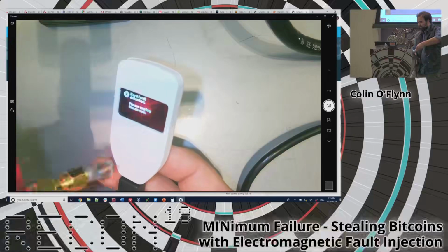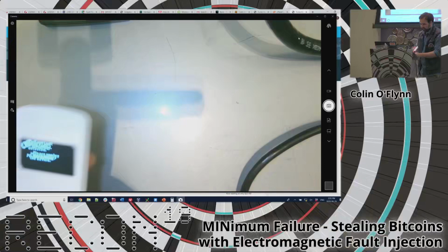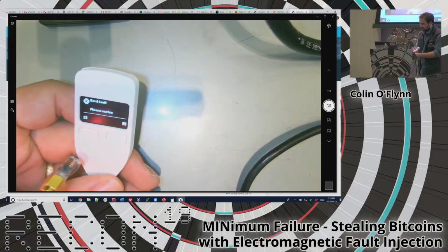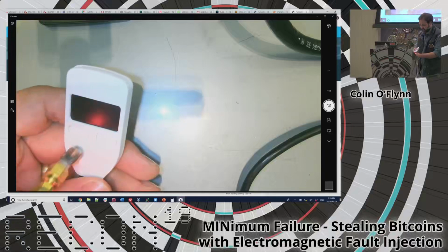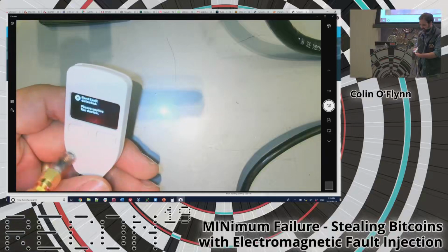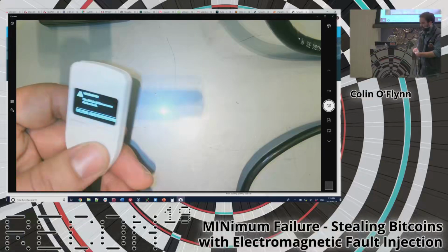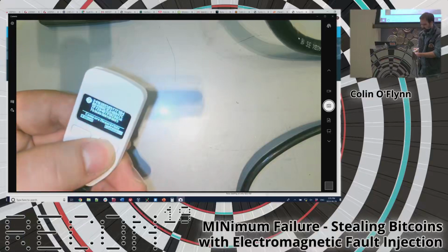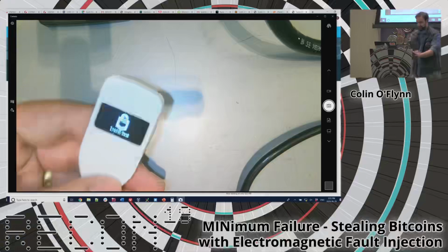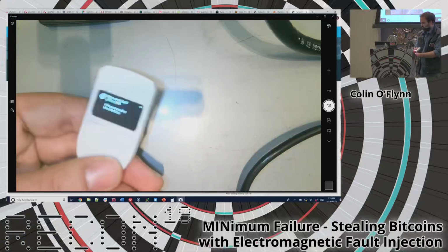There you go, hard fault detected. And occasionally what you see, actually an interesting one, is a different error. Because you saw for a second it was giving an error that the unofficial firmware detected. And so it's somehow corrupted. In fact, it seems to be missing some characters. It somehow corrupted that value. So if you do this enough, it sometimes can permanently brick it. Oh, there you go, memory fault.